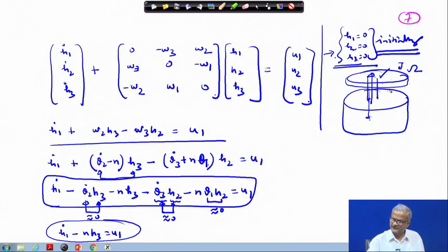You can utilize this equation and reduce it. Your objective will be to keep the satellite oriented along a particular direction, so it may be required that this part is de-spun, not rotating at all. Accordingly we have to choose their angular momentum.